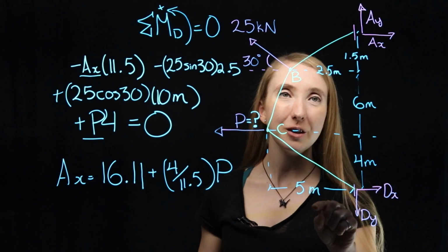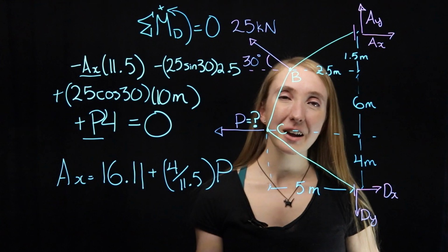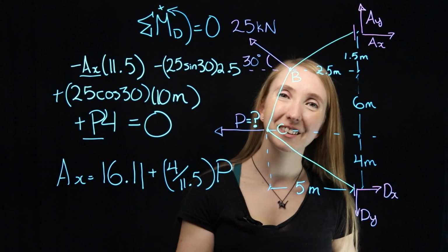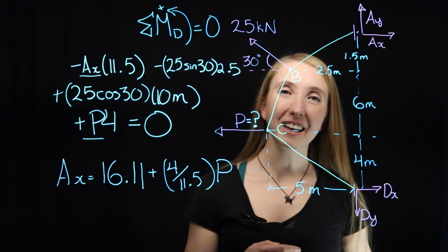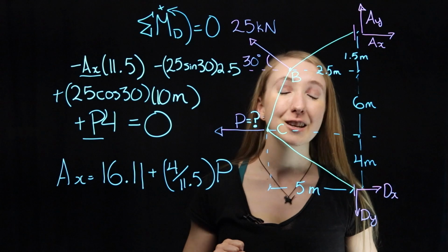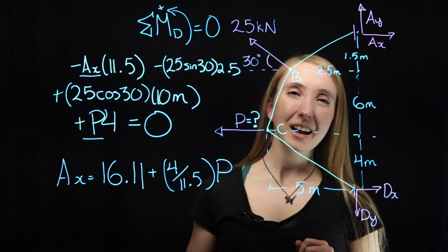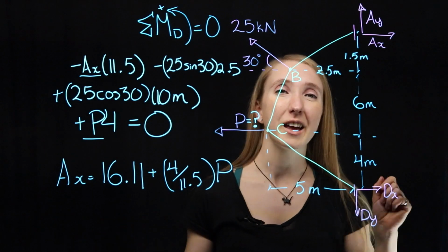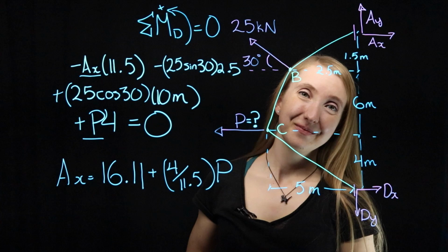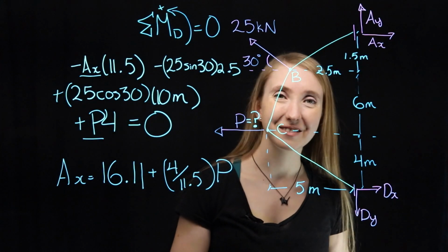Because we know the geometry at those points, we can simplify our reaction forces in terms of things we know. Second is that any equilibrium equation we write, we're going to try and write it in terms of the unknown force P, instead of in terms of unknowns like TBC, TAB, or TCD. That will let us solve directly for P.